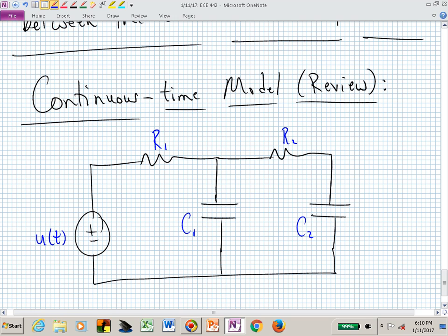What do we want to concentrate on in terms of variables that might be helpful in describing this circuit's behavior? You told me it's second order, and how did you determine that? Because of the energy storage devices, your capacitors. So maybe it's some variable associated with the capacitors. Now ELI and ICE help us determine which variable is the important one. ELI is for inductors, and ICE is for capacitors. And which variable is differentiated in ICE?